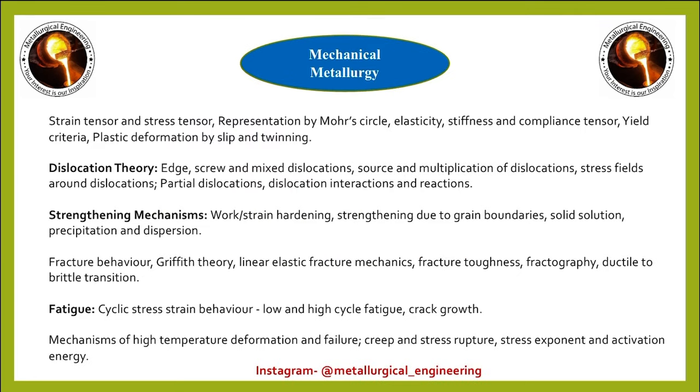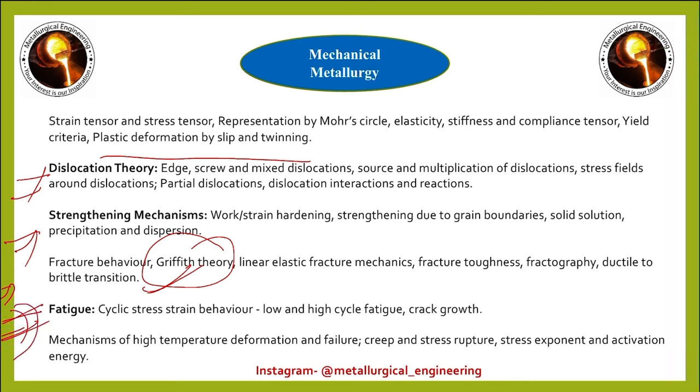You have strain tensor, stress tensor, representation of Mohr circle, elasticity, stiffness and compliance tensor, yield criteria, plastic deformation by slip and twinning. Then you have dislocation theory, strengthening mechanisms, fracture behavior, in which the Griffith theory is very important. Another thing is fatigue. Either one numerical or one theoretical question you will definitely get from fatigue. And then you have mechanisms of high temperature deformation, that is creep and stress rupture.